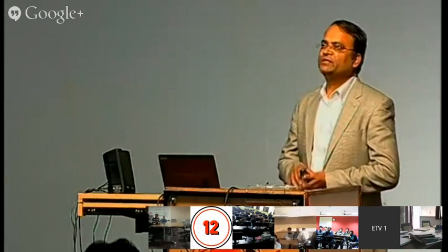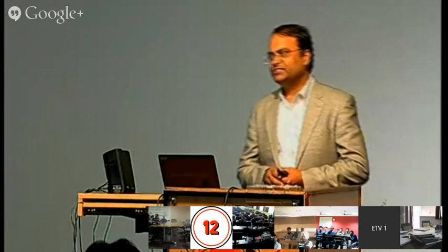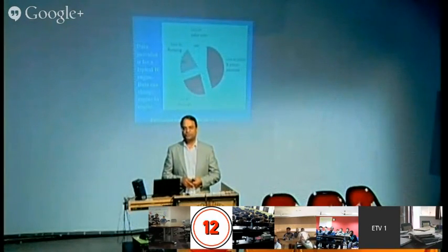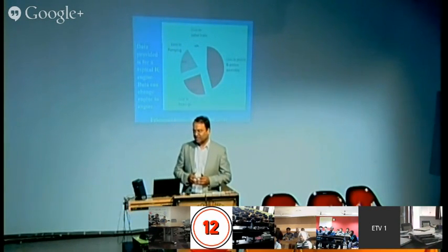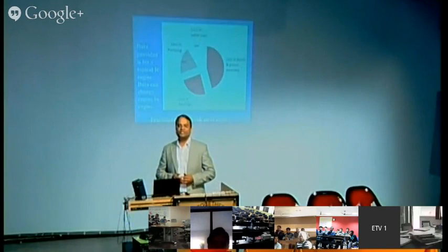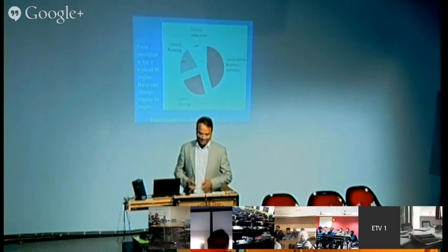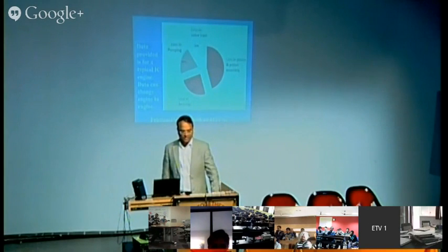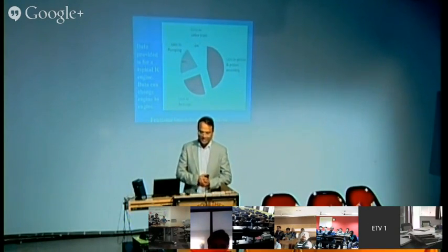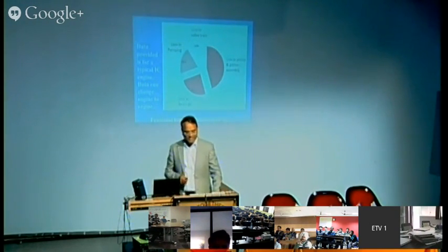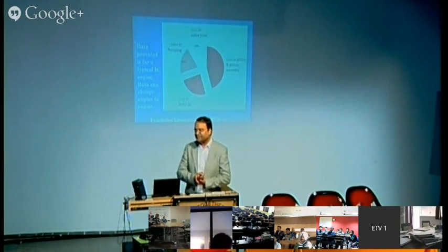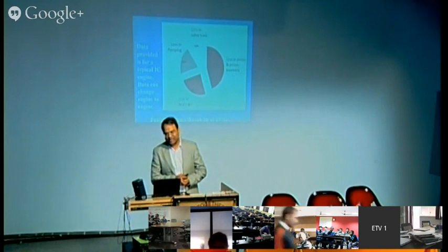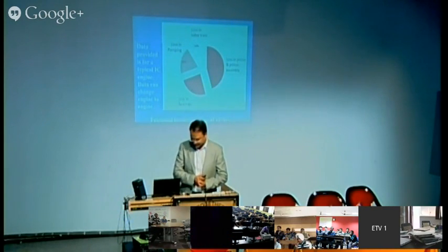Now, the 15% power loss, if we presume it as 100%, and the breakup is presented for the engine in this context, then 45% of the energy is lost at the interface of the piston ring and cylinder liner assembly, 25% is lost in the bearings, and similarly 20% and 10% are lost in the pump and valve train.